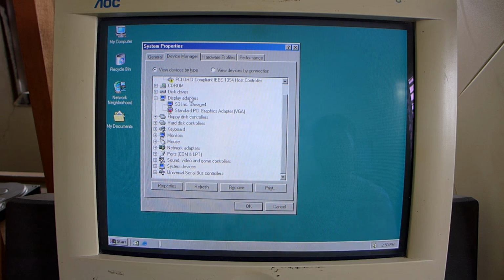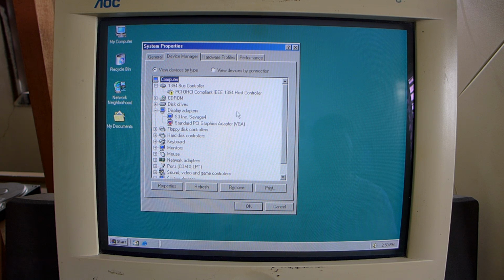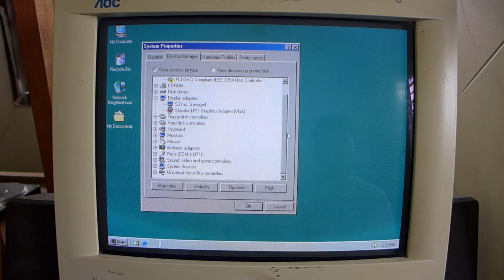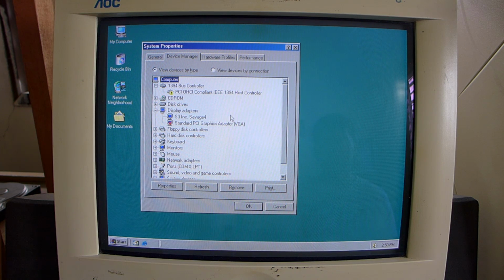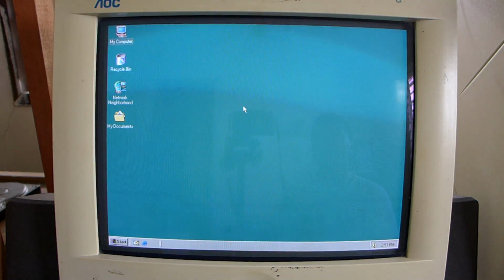Also, don't be alarmed if your development boards don't show up in the Device Manager. That's normal because the development boards are non-plug-and-play peripherals, and they behave like old-fashioned ISA cards, especially with the old-fashioned jumper settings that you have to set to the correct configuration to make it work on your system. So once that's complete, the next step is to install the SDK to be able to develop PlayStation software and then run them on the DTL-H2000 dev boards.